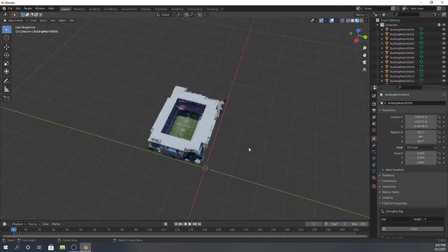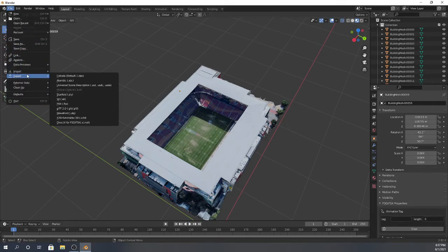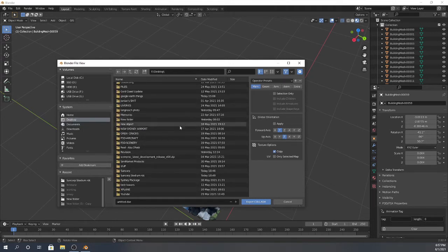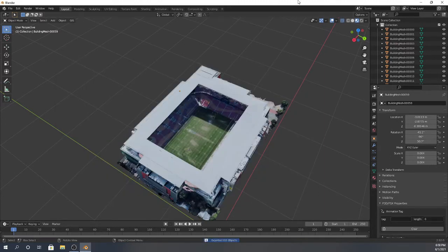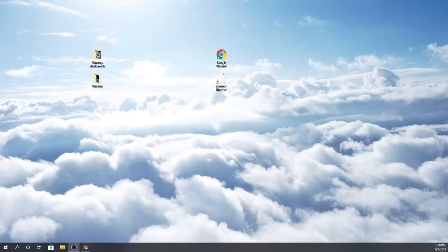The next thing you want to do is the Model Converter X stage. So just press File, Export, because we're exporting it out of the simulator, and choose this DAE file, Collada default. You should get an option for wherever you want to put it, and I'm putting it into Suncorp. Just name it whatever you want really. I'm naming it Suncorp here. Then press Export Collada. There we go. Exported 102 objects. So that is now exported, and we can open Model Converter X, which is the next stage.